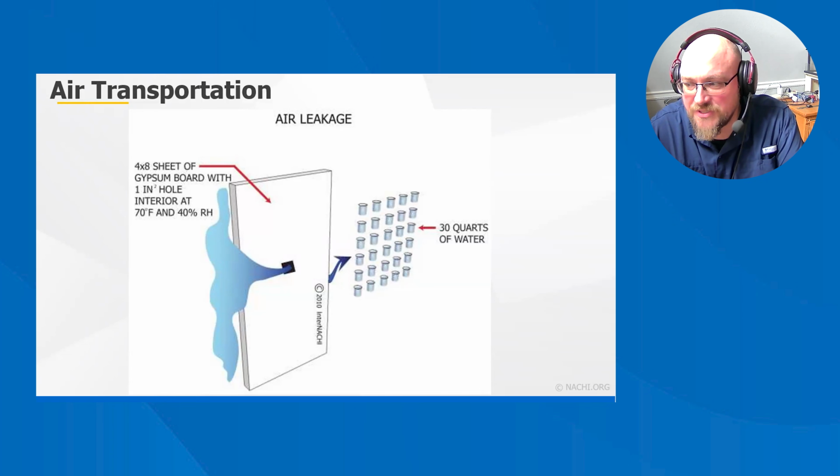Since insulation reduces heat transfer or flow, it also moderates the effect of temperature across the building envelope's cavity. In most U.S. climates, properly installed vapor diffusion retarders can be used to reduce the amount of moisture transfer. Except in deliberately ventilated spaces such as attics, properly installed insulation and vapor diffusion retarders work together to reduce the opportunity for condensation to form in a house's ceilings, walls, or floors.